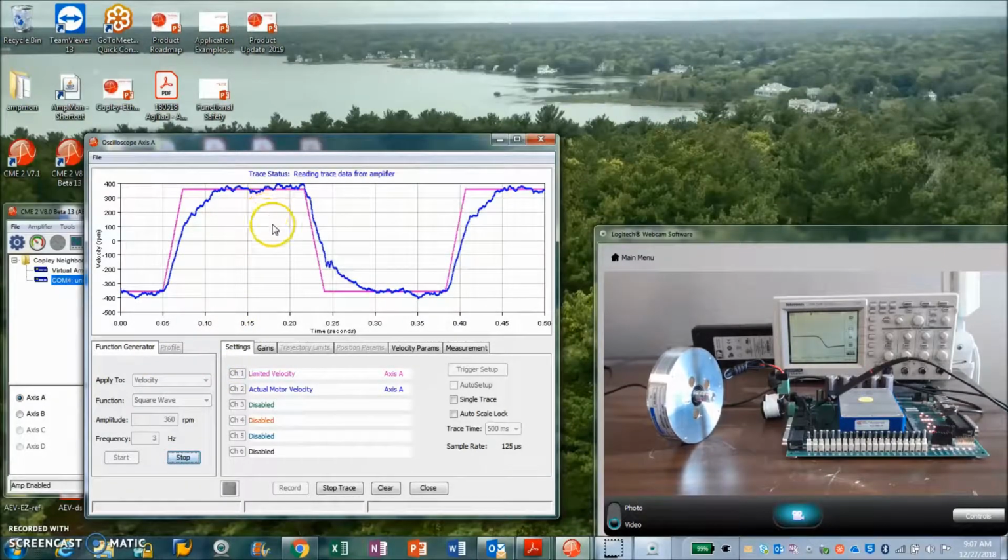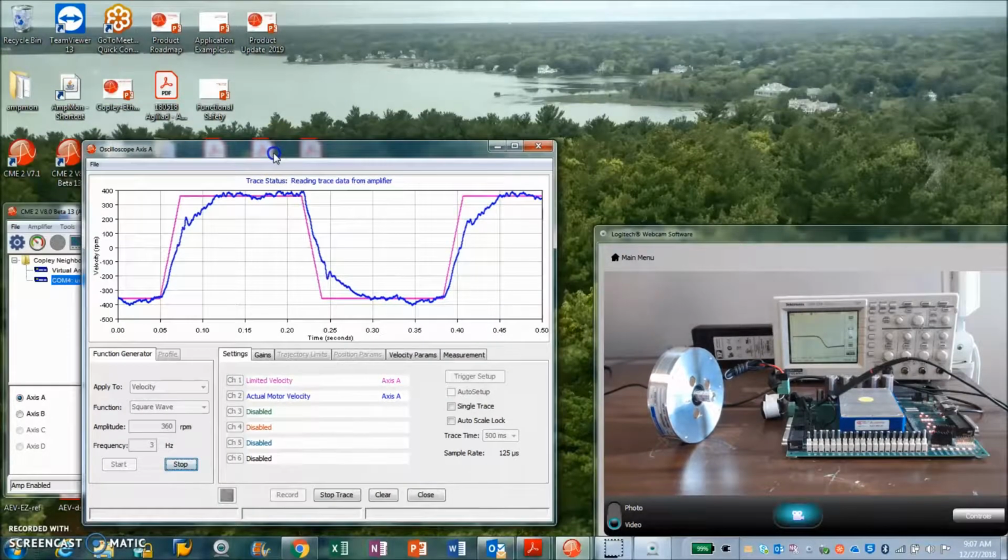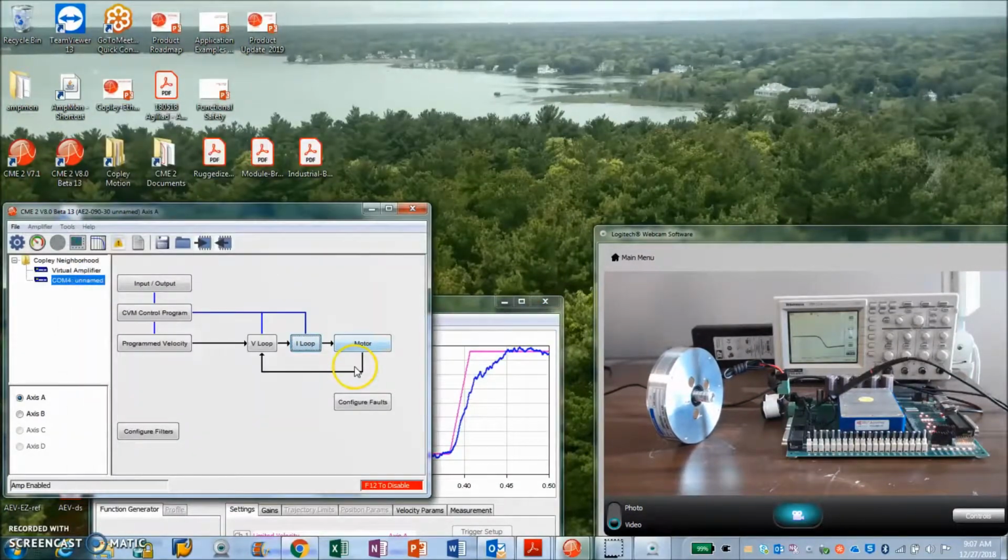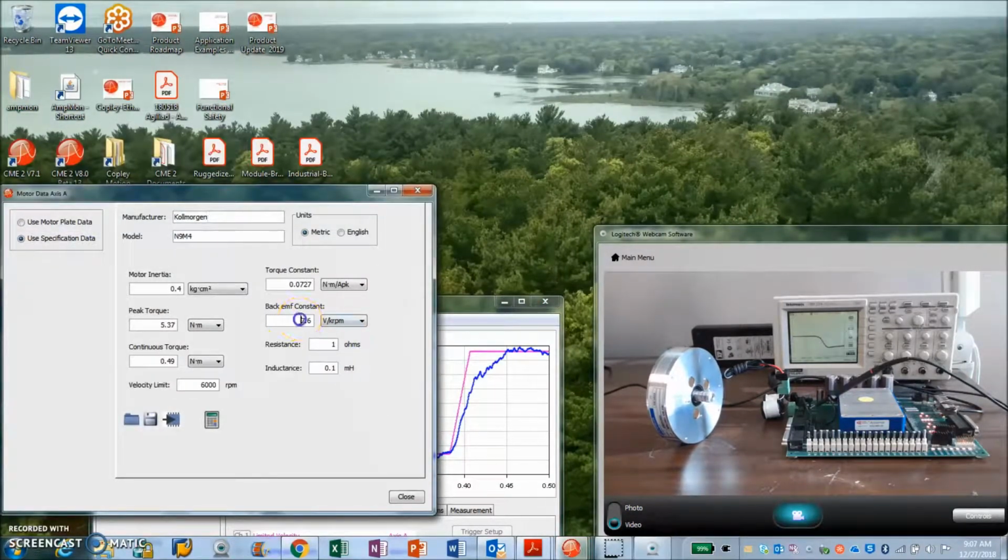And we're looking at the velocity loop tuning here. I've got the commanded velocity, a little above 300 RPM, and the actual velocity. Now, again, there's no feedback device on here like an encoder, so I'm doing this open loop velocity. And of course, this is based on a math model. If we take a look at the back EMF constant of the motor, that's volts per K RPM. If you put 7.6 volts out, you go 1,000 RPM, plus some IR drop in the motor. So at some current, you get some IR drop. So these parameters help tweak the model.